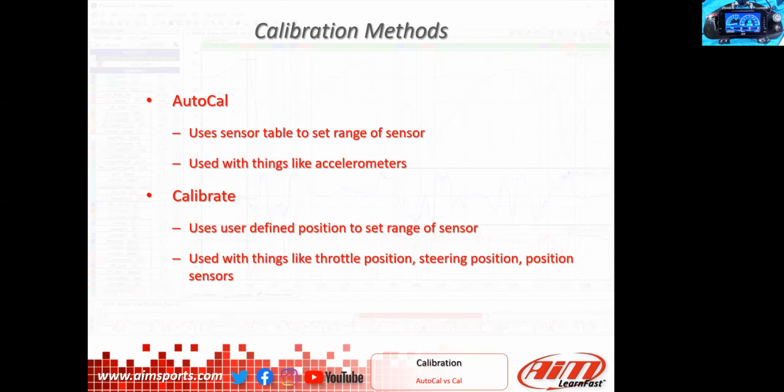Yeah, it really does vary for the use and the person doing it. For example, if you're using your suspension pots to look at some aero lift at high speeds, it's really looking at pitch, roll, and yaw of a car using the shock pots. 200 is way more than sufficient.